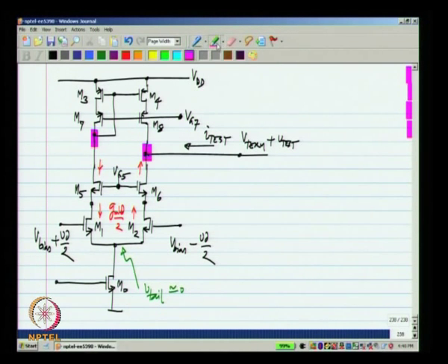Again it is useful to imagine that the NMOS transistors were ideal, that is they had 0 GDS, and calculate the contribution of PMOS transistors, and similarly assume PMOS transistors are ideal and calculate the contribution of NMOS transistors. It turns out that the resulting output conductance is a sum of these two. You can do the analysis separately and then do the analysis together, so that you do not get bogged down by complexity.